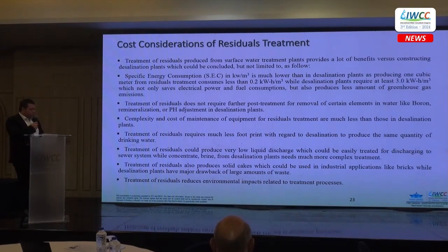Treatment of residuals requires much less footprint as you don't need to construct an intake like in a desalination plant. Treatment of residuals could produce very low liquid discharge, which could be easily treated for discharging to the sewer system. Treatment of residuals also produces solid cakes, which could be used in industrial applications like bricks. Also, treatment of residuals reduces environmental impacts related to treatment processes.